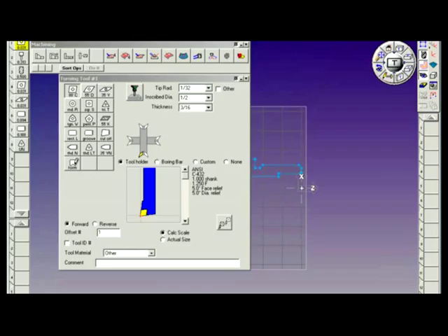If I select other, I can define an insert of my choosing, but I will not see a tool holder. Going back, unchecking other, and activating the tool holder shows us the tool holder in the proper orientation. The red plus sign represents the touch-off point on the part.